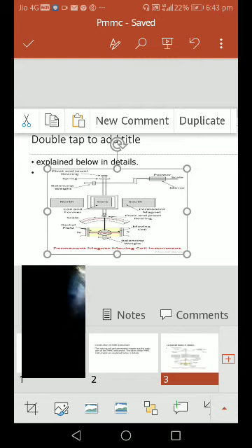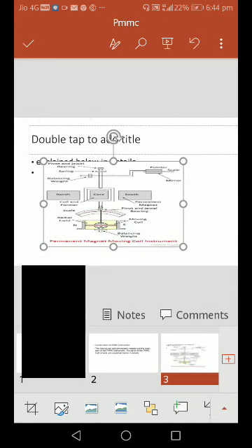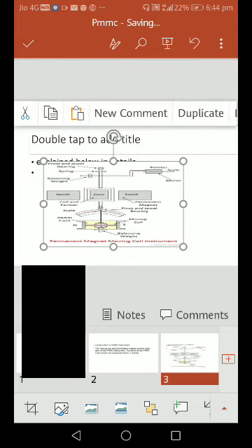When the coil moves, the magnetic field is cut by the conductor to produce an EMF. The coil is deflected, and the pointer indicates the reading on the linear, uniform scale.